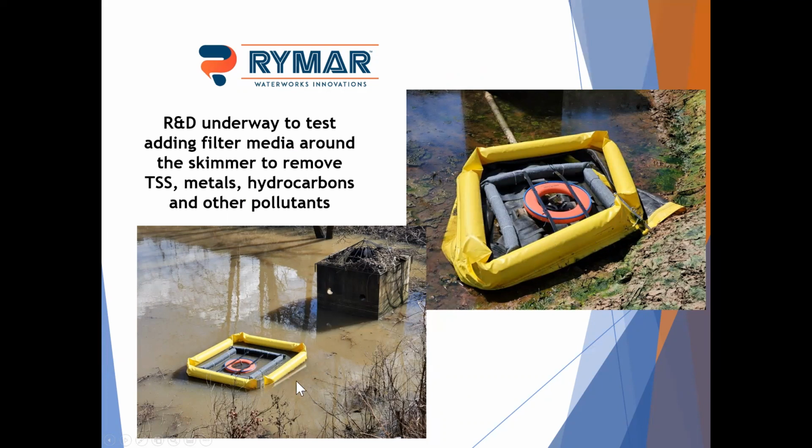The outer filter is a woven material, more of a screen, and then the inner is a non-woven material. Both of these help remove TSS. The inner is also treated to treat bacteria. It'll also absorb hydrocarbons. We're working to see if it can affect metals. And what we're really hoping is to find a solution for phosphorus and nitrogen, but we haven't gotten there yet. But we have some ideas we can help with that if you need to.